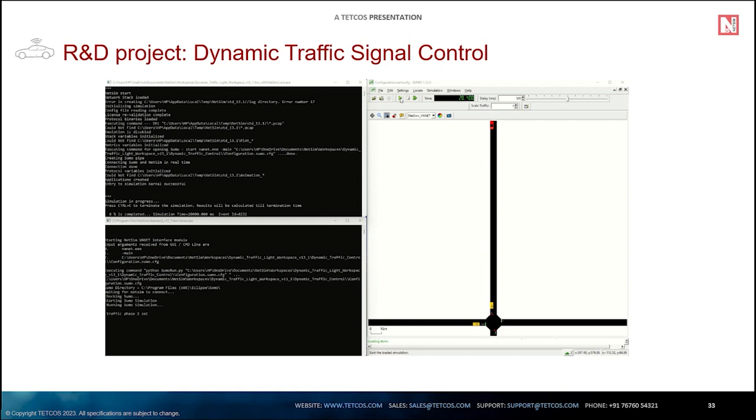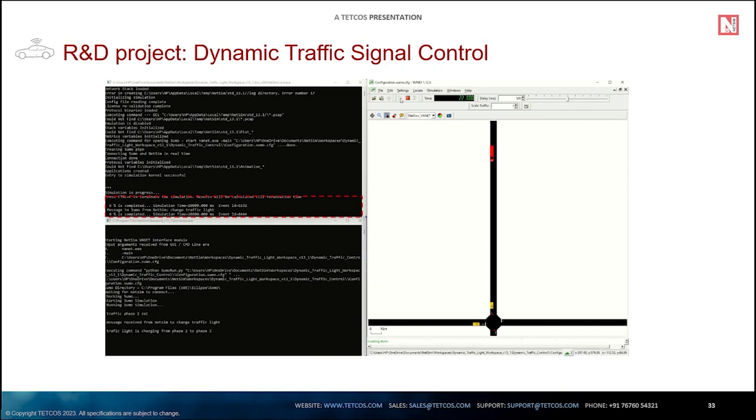With this code change, we see that when emergency vehicle is at some distance d1 away from the junction, the EW lane switches to phase 2 with green to clear traffic. Next, when the emergency vehicle is at a close distance d2, the signal switches to phase 3 with yellow light in the EW lane to alert vehicles in that lane to halt.